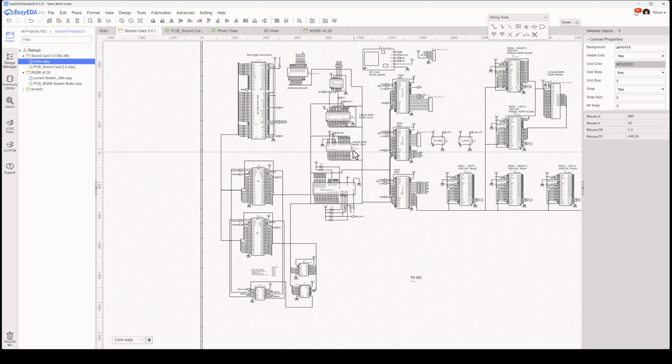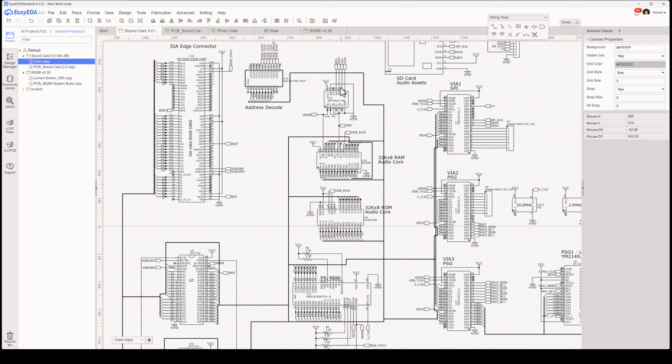And if I zoom back out, here's my ROM and my RAM for that 65816. It's 32K ROM, 32K RAM, which is plenty adequate for what I'm doing here. Above that, I do have some additional logic to invert the reset signal coming in. The 286 uses an active high, the 65816 system uses an active low, so I've got to change that around. Just some basic inversions of some things here, like read-write. This is all to support the read-write logic within my 65816.